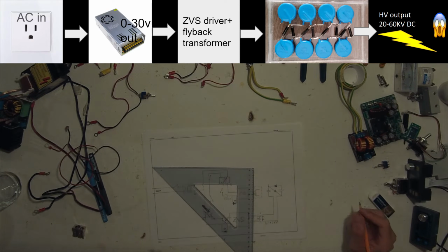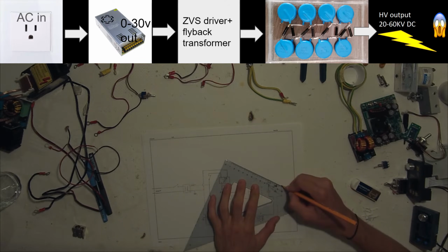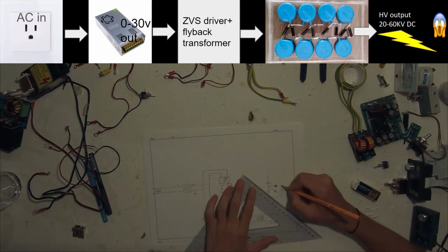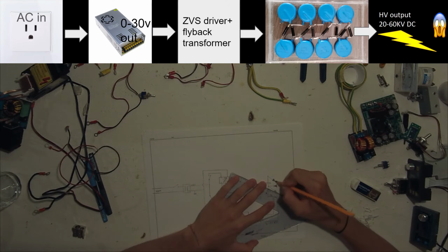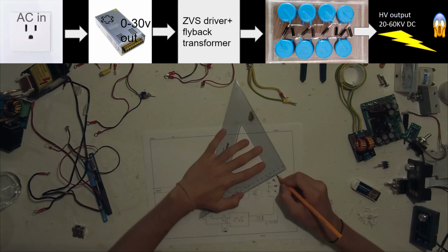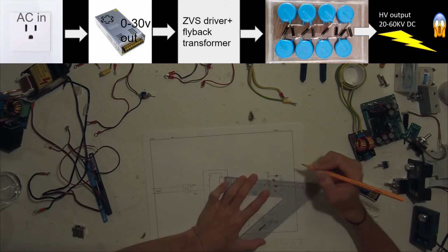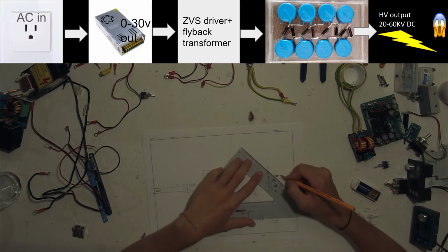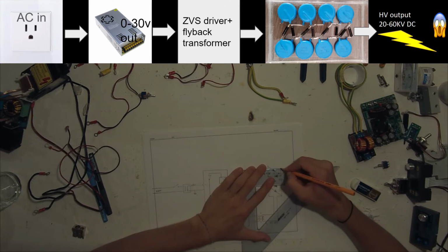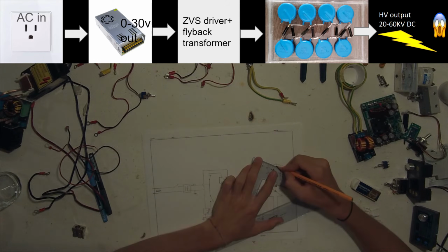And the next component is the Cockcroft-Walton voltage multiplier, that is an array of capacitors and diodes put in a particular configuration so that they simply multiply the input voltage by a factor that is simply the number of stages. So in my case I have 4 stages, so if I input 10,000 volts, the output will be 40,000 volts. Obviously there will be some losses due to the inefficiency of the system and other factors.